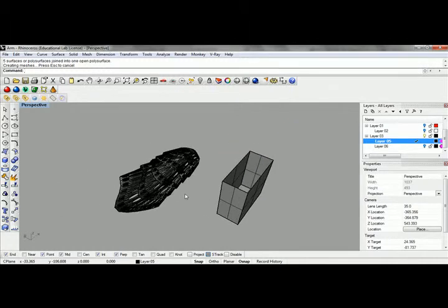And so what we want to pay attention to when setting up the model is what printer we're going to be utilizing and what the tolerances are for that. The Z-Corp powder printers are very accurate, but they tend to make very, very fragile models. You don't really want to model anything for those particular printers beyond probably about 0.09 inches thick, and that's just at an absolute minimum. Otherwise, you won't be able to extract the model.